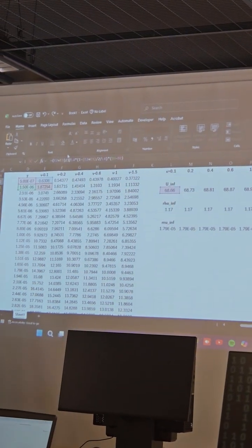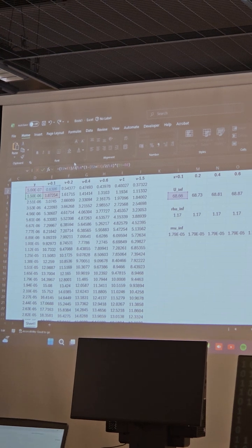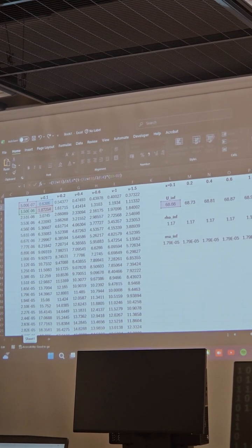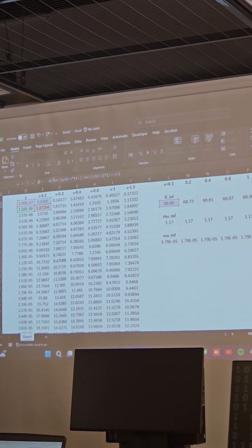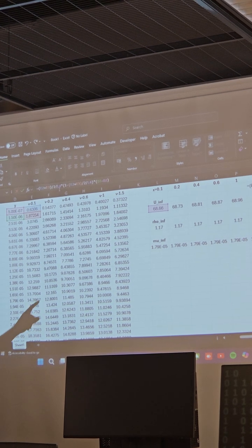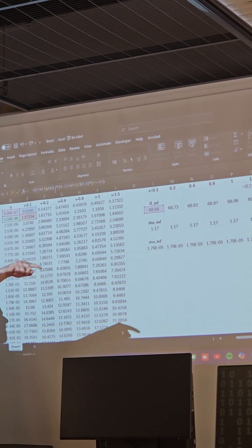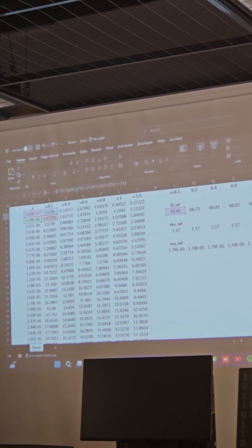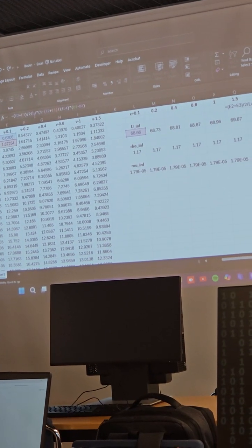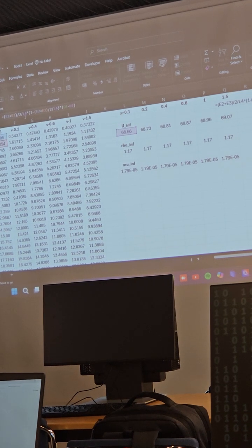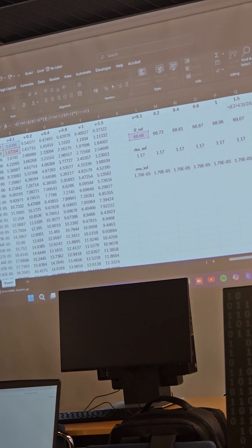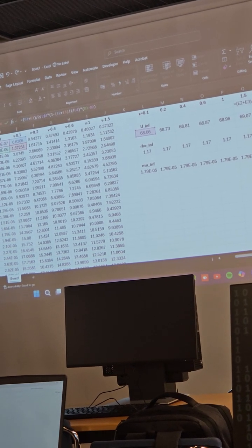And if you want to pull that in different directions, what you need to do is lock some cells. For example, you can lock the cell related to L4 for me. So this is U infinite. When I'm pulling for different axes, I can do that, so I don't need to lock the letter. But when I'm moving that for the Y, I need to lock the number. So if I lock the 4 with the dollar, when I'm pulling it on the number, then it doesn't change.